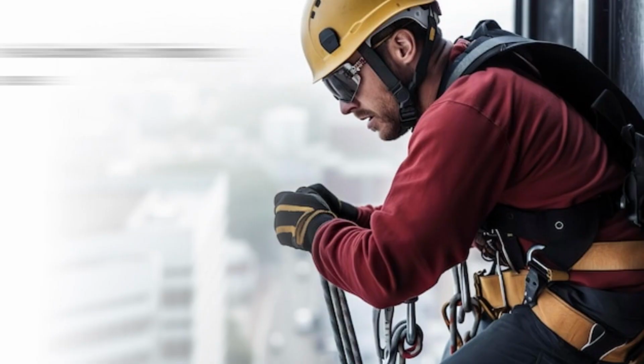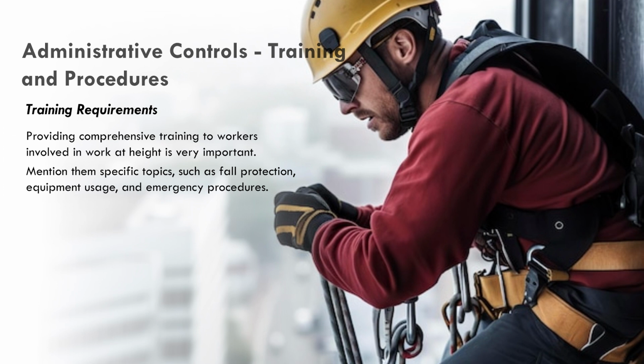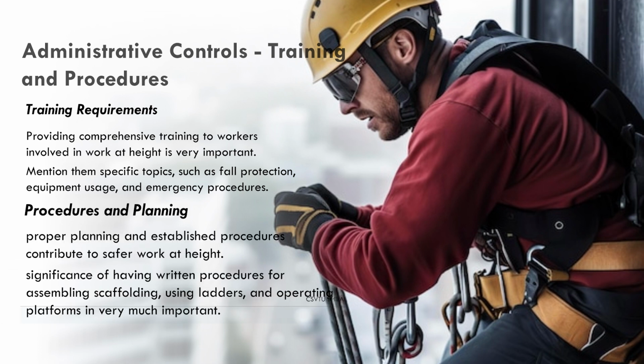And then administrative controls, which include training and procedures. Training requirement. Providing comprehensive training to workers involved in work at height is very important. Mention specific topics such as fall protection, equipment use and emergency procedures. Procedures and planning. Proper planning and establishing procedures contribute to safe work at height. The significance of having written procedures for assembling scaffolding, using ladders and operating platforms is of very much importance.